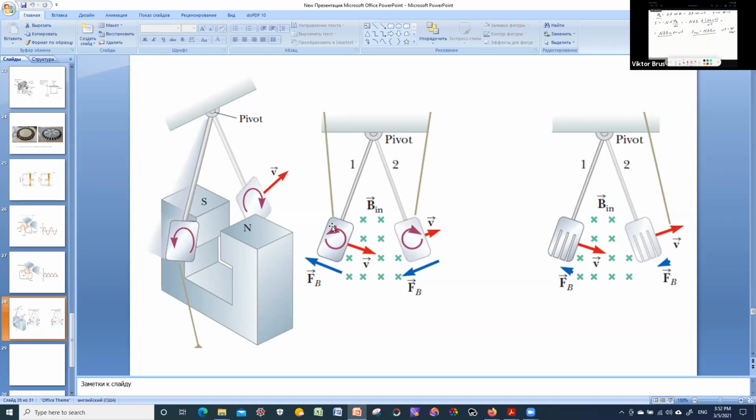Since electric power is a product of electric current magnitude and voltage, and there are two electromagnets responsible for each of these parameters, their common effect on the spinning conditions of this disk results in calculating the total power consumed within the network. So even some negative parasitic effects sometimes find practical applications.